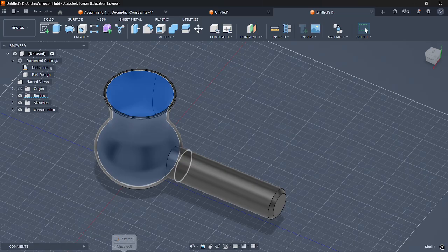So if you change the order, it'll create slightly small differences in your part. But you can only change these orders if certain things aren't dependent on each other. So right now, I want to make this shell after this chamfer here. So what you would do is select the feature and just drag it. But you can see I'm moving my mouse and it's stopping right before that first fillet that we made.